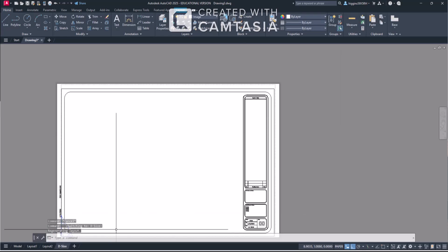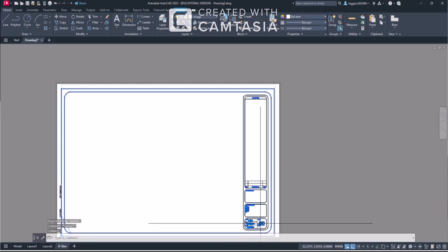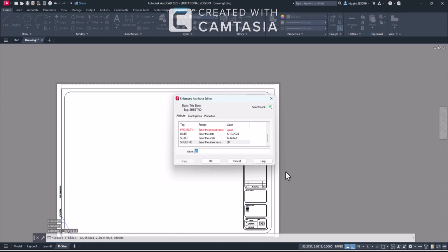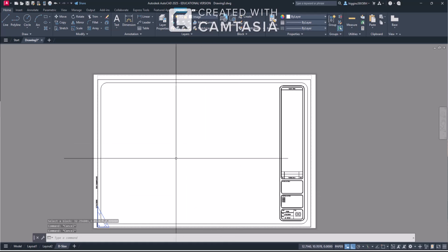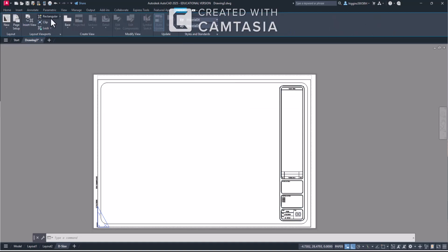It's put in the title block, where you can also double click here and put in all the pertinent information. Make it up, make the firm, make whatever building it is, put all that information in. But of course the date should be the date, and the scale should be the scale. Next thing we want to do here is create our viewport. Again, you're going to have to create a layer for viewport, and then create the viewport. Again, we can use layout, you can use rectangular, choose rectangular. We're going to draw it in.